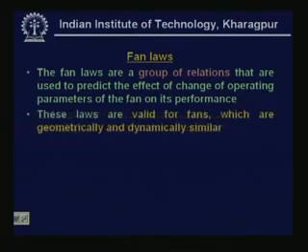And these laws are valid for fans which are geometrically and dynamically similar. If the fans are geometrically and dynamically similar, you can apply the fan laws. If they are not geometrically or dynamically similar, you cannot use them. For example, you cannot use the fan laws for comparing performance of a forward curved blade with a backward curved blade. They are not geometrically similar. So, you cannot use fan laws for these two.